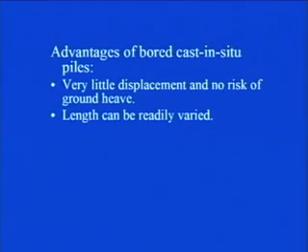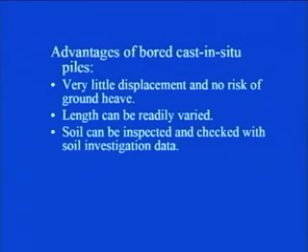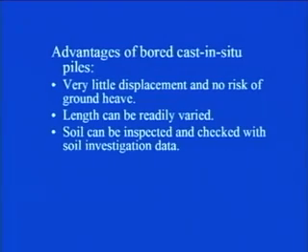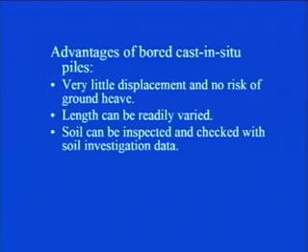Length can be readily varied. Soil can be inspected and checked with soil investigation data. See, when you will be creating the void or excavation, whatever is the soil that you are taking out, you know at which particular depth you are taking that soil out. By examining that particular soil and by comparing with the soil exploration data, it gives you the check whether your soil exploration data is proper or not. It just confirms that information.